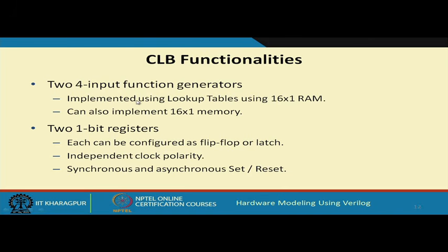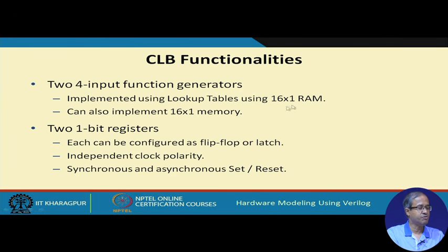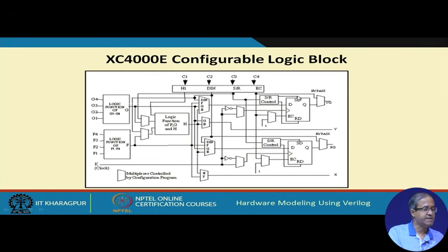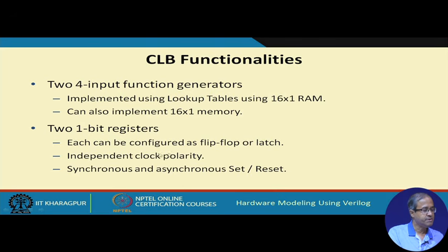In addition to implementing 4 input functions, it can also be used as a memory if you require 16/1 memory. And also inside you have seen that there are 2 flip flops, there are two 1 bit registers, they can be configured as a flip flop or a latch. Clock polarity, you can have leading edge triggered, falling edge triggered, set reset, all these facilities are there.